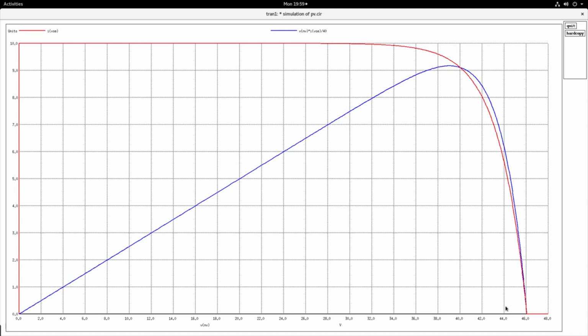What we have now achieved is that we are able to have a PV source symbol where I can scale the value of ISC and VOC, and the same symbol you can use for any PV application, and it gives you almost the IV curve, like an expected photovoltaic cell characteristic, as against the original model where we used the diode and current sources and kept on putting them in series and parallel.